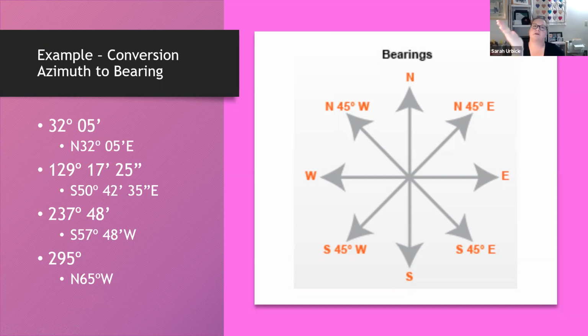All right, so we're going to back off of the straight north line and figure out what that angle is between our line and the north line. So that's why we stop when we get to east and west going outward, because we're measuring off of that north line. When we're down below, we stop at east and west again, because we're still just measuring off of that line until we get to due east and due west.